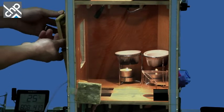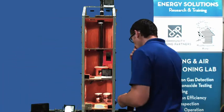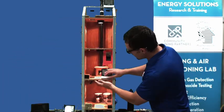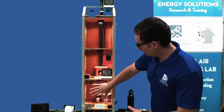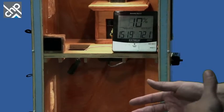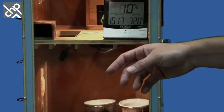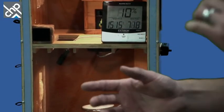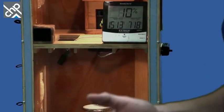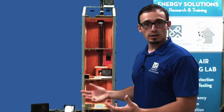Okay. So now we've added some moisture to the equation. I've got this probe, which is going down into this kind of basement level. I'm expecting that as that water starts to vaporize and boil in those little butter dishes, I'm going to see an increase in my relative humidity. When I see an increase in relative humidity, I'm also going to see an increase in my dew point. And that's where things are going to get interesting.